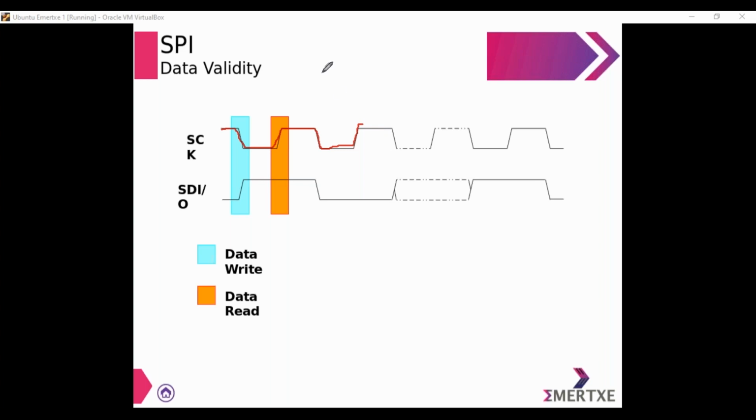The transmitter was transmitting a parity bit, and the receiver was also calculating the parity bit depending on the data it had received. When the parities are compared, if it is a match, it was concluded that the data received is proper. But when it comes to SPI, we don't have such a mechanism. We generate the clock pulse and communication happens with respect to the clock pulse.